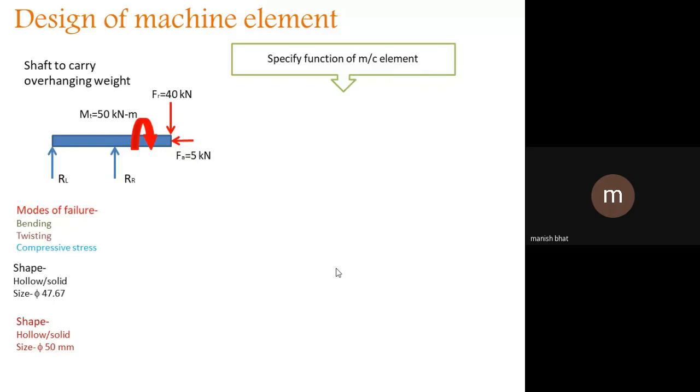Suppose I want to design some lever. You have learned the lever-operated safety valve in the case of a boiler. What is the duty of a lever-operated safety valve? Why is that lever-operated safety valve provided? It is a safety valve. Once a particular pressure is reached, that valve will blow and steam will escape from the boiler.